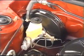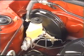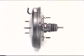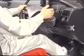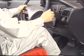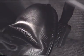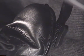If there is a problem with the brake booster, it could cause unexpectedly strong or inefficient braking. There are several, although not perfect, ways to inspect the brake booster. First, check air tightness. Stop the engine after running it for 1 or 2 minutes and depress the brake pedal as usual. Check that the pedal reserve distance increases as the number of times the pedal is depressed increases. This indicates that the vacuum inside the brake booster is released every time the pedal is depressed.